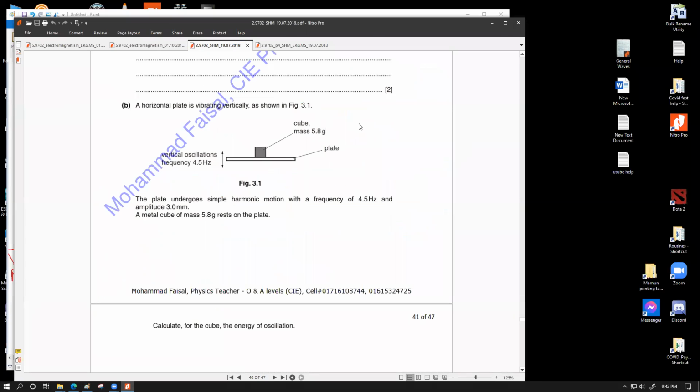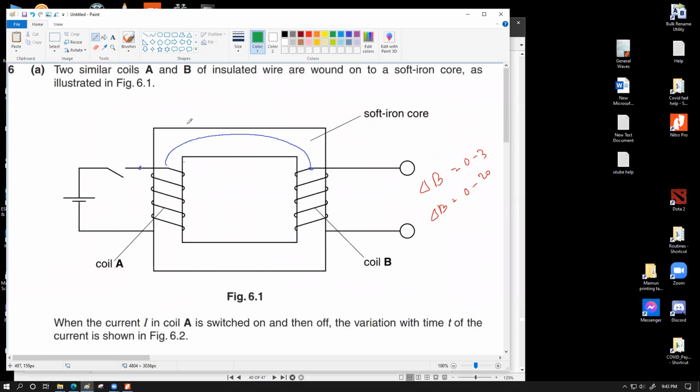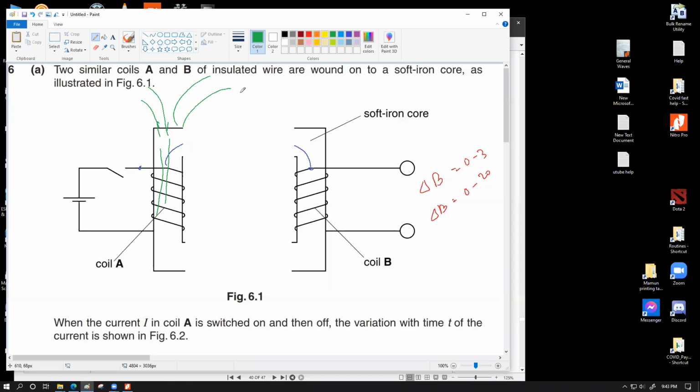So you are proposing what if we don't have these, only 2 iron cores individually connected, and they are just hanging in space, something like this? Yes, sir. Well, that basically is not of any benefit for us, because essentially the coils would be producing their own magnetic field. You would have the concentrated field lines up to the end point of this, but from the end point the spreading would still happen. You're not essentially stopping the spreading.